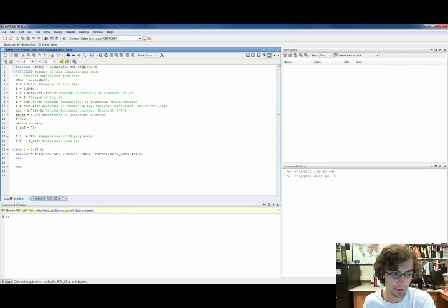This is just some constants that I'll need. I guess I can show you the ode45 function file first. This is my ode45 function file. This is what I'm using method of lines in. This is what is going to give me that unsteady state temperature profile for each individual position.